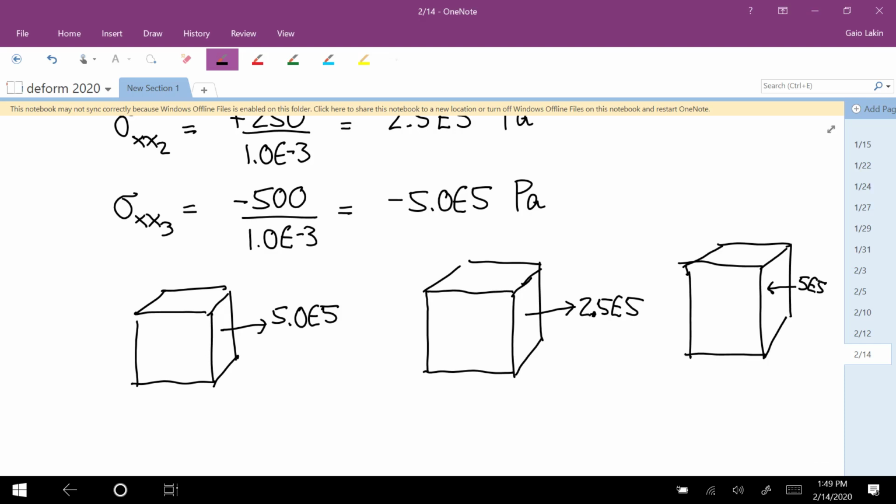All right. One thing that's sort of interesting, and now those represent stress tensors, so you could go to the stress tensor and then you could calculate principal stresses and whatever. Well, what's the principal stress tensor for, let's say, this one? Do it in your head. Yeah, right, it's already principal because the only stress is normal.